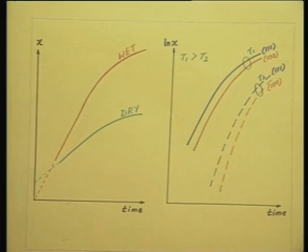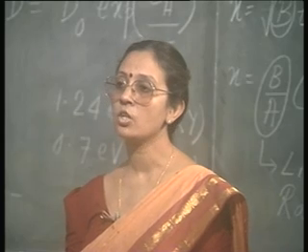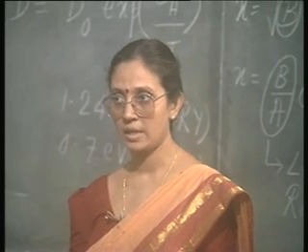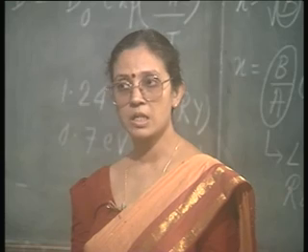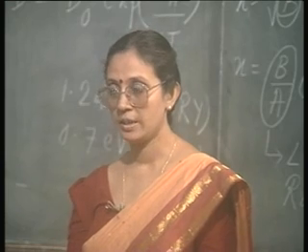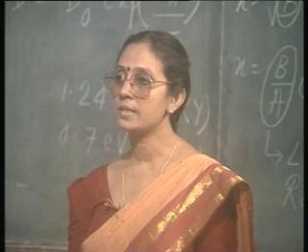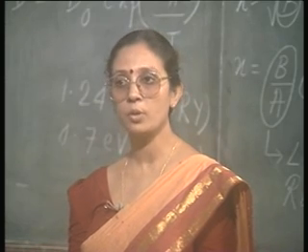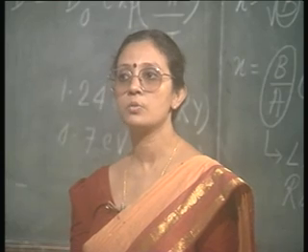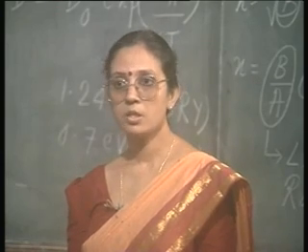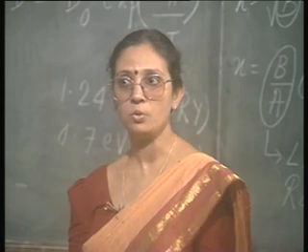Now, you see, if I started with a fresh silicon surface, I have made sure that there is no oxide on it at the time of starting the oxidation process. Then I would expect that both these curves will pass through the origin, that is, at t equal to 0, the oxide thickness should be 0, because I have made sure.